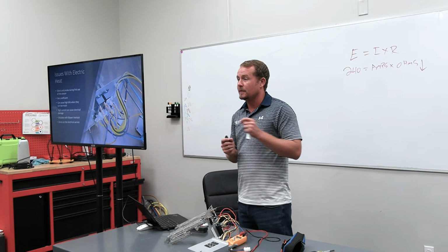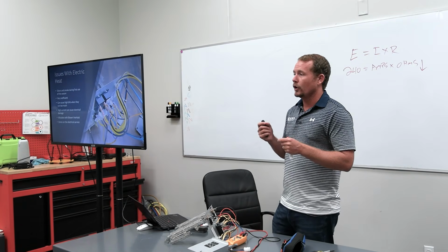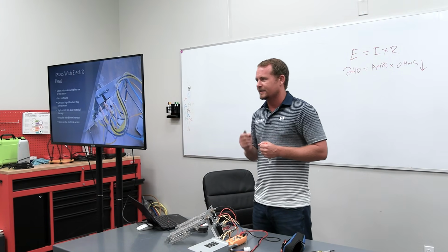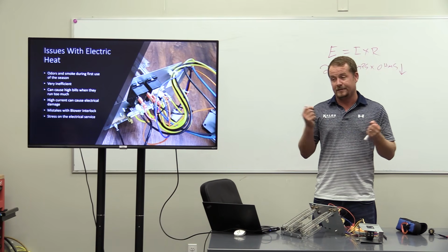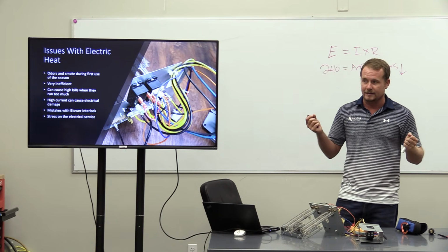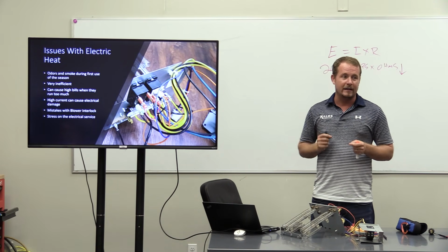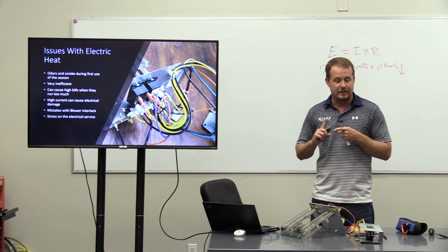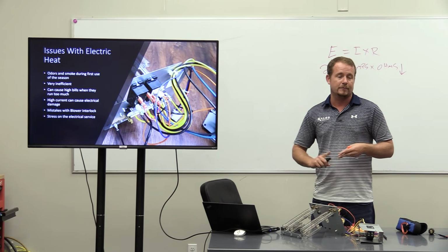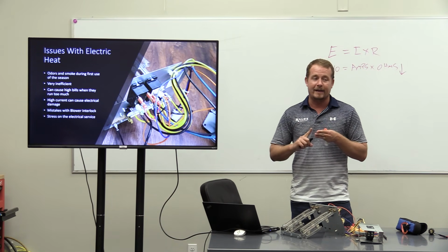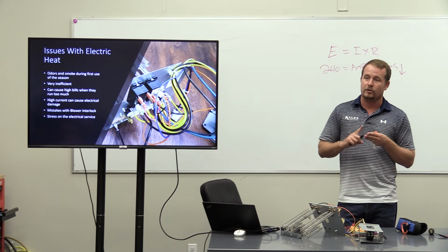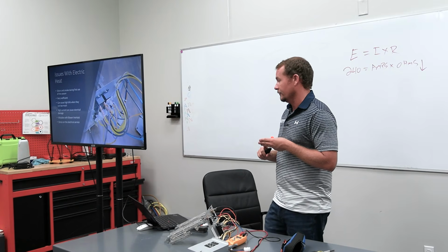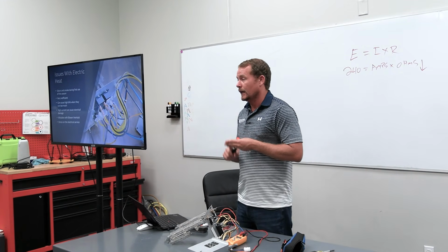One of the big mistakes I see people make, one of the things I want to protect you from, is when you're a genius because you've gotten good with electricity, and you know how to diagnose things and rig things together. When you're dealing with electric heat, and this is also true of gas furnaces too, don't go in and start rigging things up without paying attention to the wire sizing you're using, and making sure that those electric heat strips go on when they're supposed to, go off when they're supposed to, and aren't run through a relay that can't handle that current. That was a complicated sentence. The point is, don't run it through some sort of control that can't handle the current. That's easy to do because it's a lot of current.